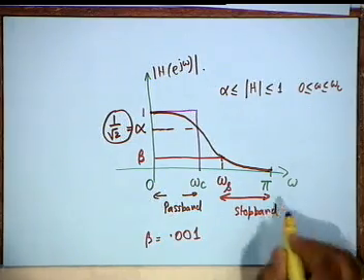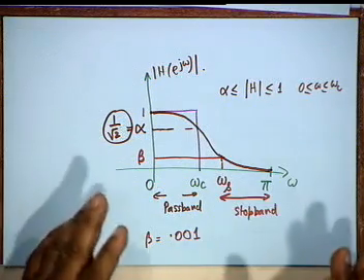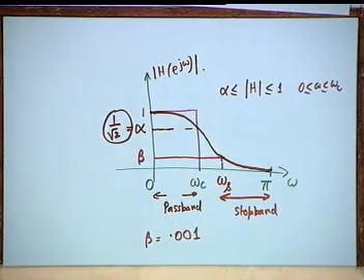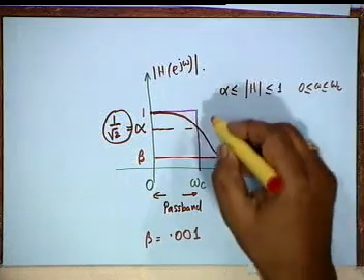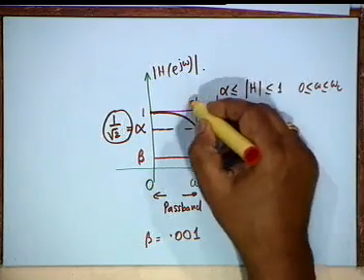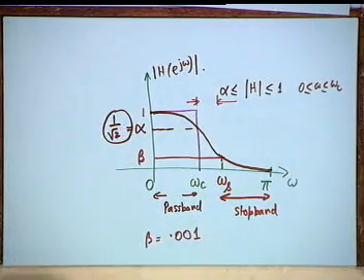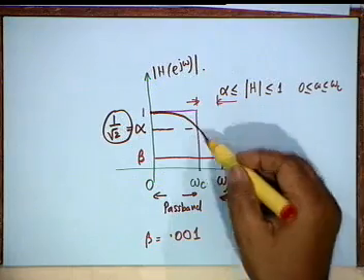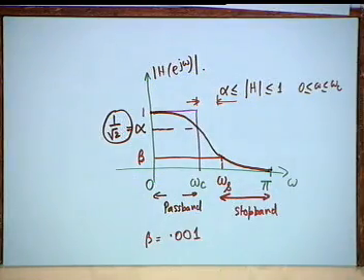That is, whatever may happen elsewhere within the stop band, the signal must be attenuated by at least the amount specified. It could be 60 dB, it could be 80 dB. The in between region, which unfortunately is a fact of life, that is between omega c and omega s, has to be permitted, because from omega c it cannot come to beta immediately, it cannot make an abrupt jump. If it does, then again non-causality shall step in. Nature abhors sharp transitions.